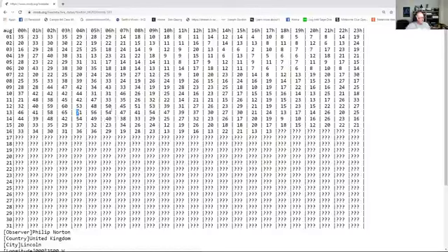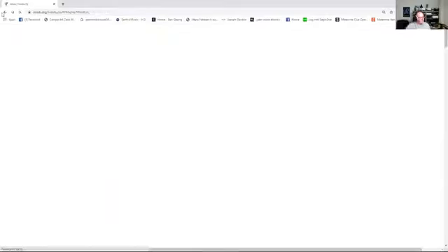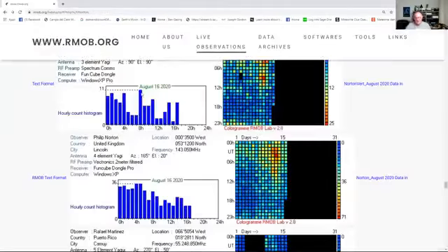But I've had in excess of 100 in an hour with my own setup, which I have to say was very well configured because I spent hours on it making sure. Because what you don't want is, when your next door neighbor turns the light on, for you to detect a meteor. So you have to set the threshold just about right so you're minimizing interference, but you haven't set it to such a level where you can't pick anything up. But that's basically what you can produce.